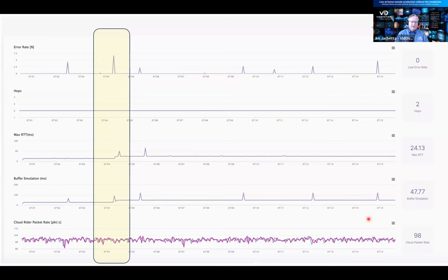With the bonded cellular products, it is a little bit of trial and error. If we see packet loss in the payload, in the video and the audio, we increase the latency, and you need a human being to do that. We can't adapt. Our modern products can go down to 250 millisecond buffering even over cellular, but that's pretty aggressive.